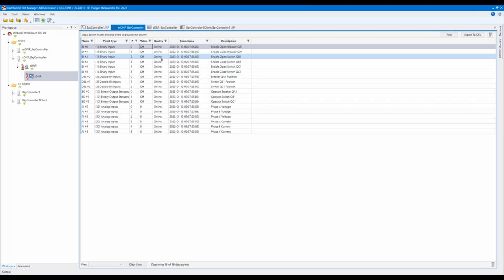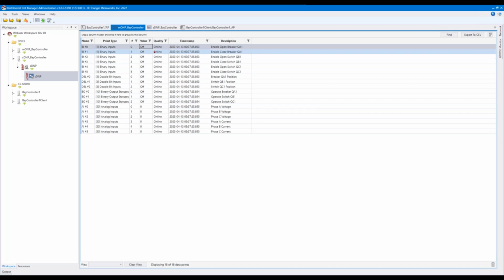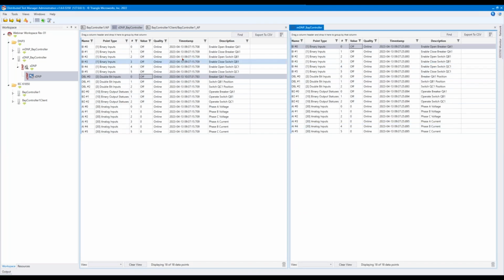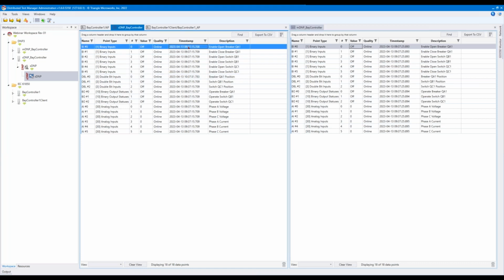All right, the first thing you'll notice is that it looks pretty much the same, and that is by design. The database on your DNP3 outstation is going to match the one on your master. But the way that you create these two databases is fairly different. First I'm going to drag them down side by side so that you can see them next to each other. On an outstation, the data map is either created by the manufacturer or vendor when the device is made and then provided to the customer in the form of maybe a PDF, an XML DNP device profile, or possibly a spreadsheet. But it essentially just is what it is.